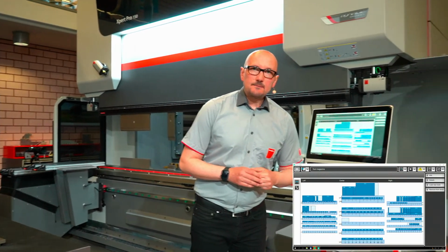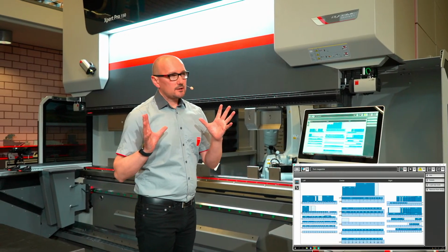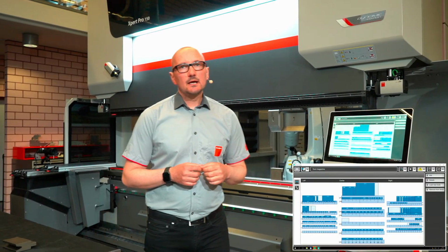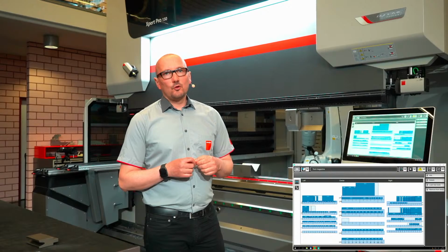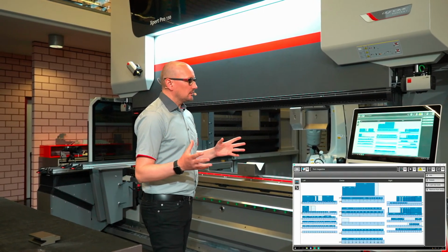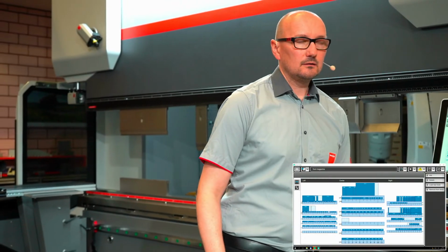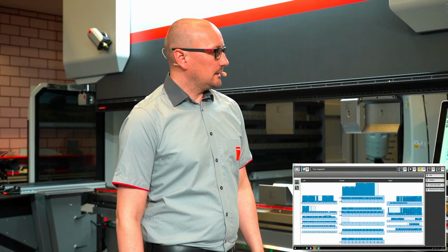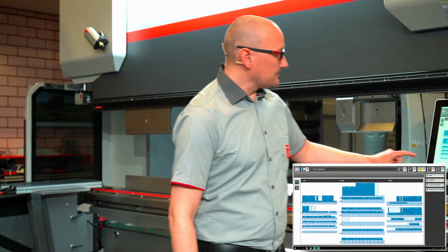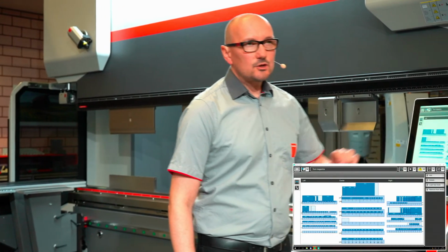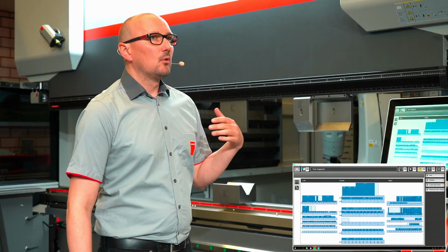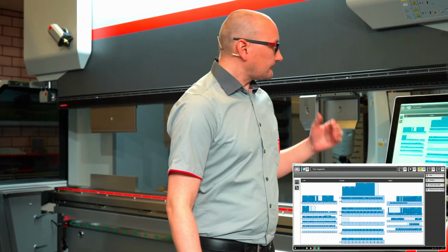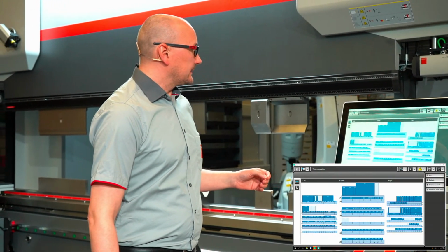Maybe one interesting point is, if you place the modular tool changer on a 3 meter machine, you can store around 42 meters. If you have a 4-meter machine, then it's of course a little bit longer. The place in the center position is a little bit longer, and we can place up to 52 meters in our machines. This depends a little bit on what configuration you have. You can also say you need more space for top tools or more space for bottom tools, and this affects it a little bit. But that way you have a number you can calculate with.